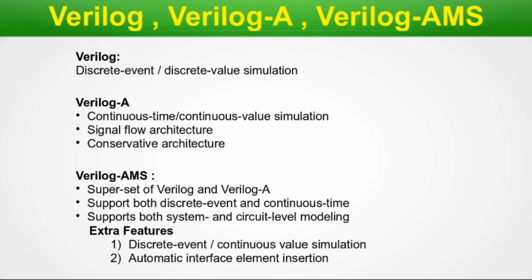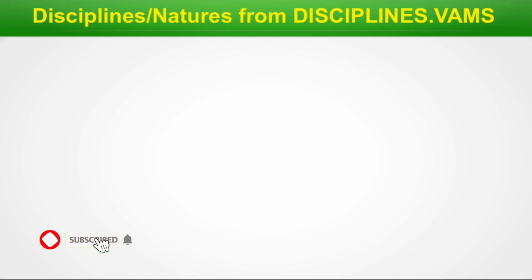Automatic interface element insertion. So an interface element is a particular element that actually stays in the boundary of the digital and analog, and it helps to convert one into the other. Okay, here we cover the relation, correlation, interconnection of Verilog, Verilog-A and Verilog-AMS. Let's move on to the next slide.